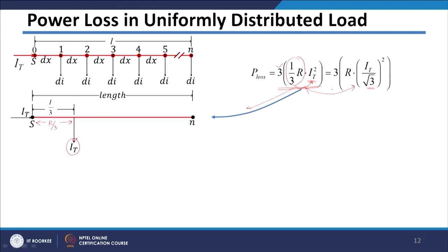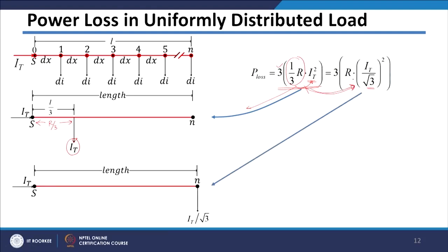Now, this same equation I have written in another form, and if you plot the figure or if you lump this load using the equation which is shown on the right hand side, you can see that here I am taking total resistance into account, means I have to take full length of the feeder into account.